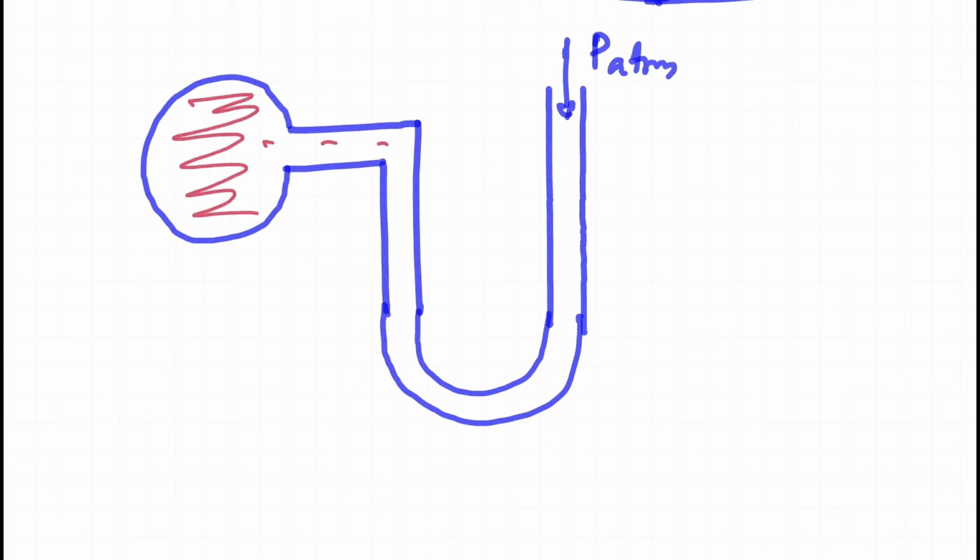heads. So what's different in this arrangement is the pressure in the pipe is less than the atmospheric pressure. So P1 is less than the atmospheric pressure in this case. So you have the liquid flowing through the pipe, and you have a certain height of the liquid. And then the pressure in the pipe will decide how much the second fluid, or the manometer fluid, will rise or lower.